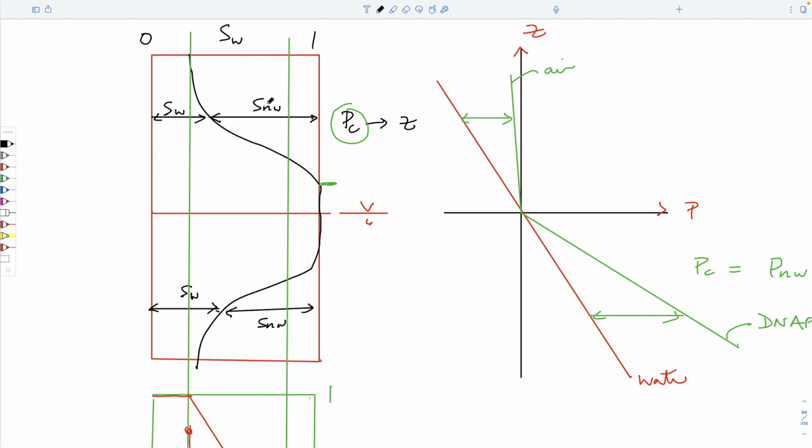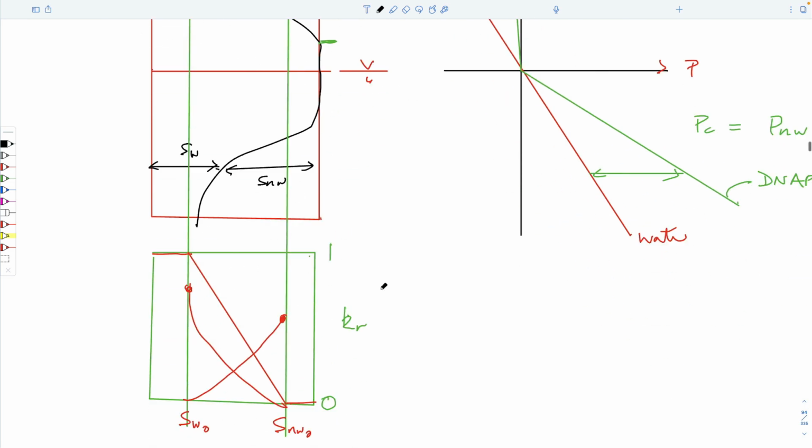And if it's air, that's great. That's what we've just defined for these Van Genuchten relationships, capillary pressure and relative permeability curves for air and water systems, the water phase in this particular case. But it also applies if the non-wetting phase, instead of being air, is a DNAPL. And everything that we've done with those applies in that particular circumstance. And we should be able to make the transition. And I think that's it.